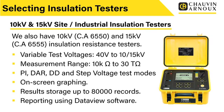And these have got all the features that I've just talked about with the 5 kV products, but they also add a few extras on as well. Obviously the increased test voltage is part of that. So we have variable test voltage, in this case from 40 volts up to 10 or 15 kV. We've got a measurement range from 10 kilo ohms all the way up to, in this case, 30 tera ohms. We've got the ability to do all the usual stuff, the PI, DAR, DD and step voltage test methods.